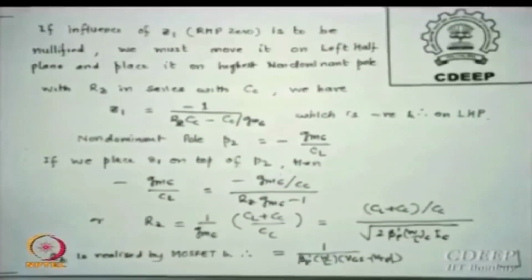So I will cancel that P2 once for all because P2 was necessary with this CC. So I say CC I don't want to increase too much. Is that clear? Now I say okay, if that split has to be, then why was the split necessary? Because P1 and P2 are very close. So stability, phase margin, was an issue for me.